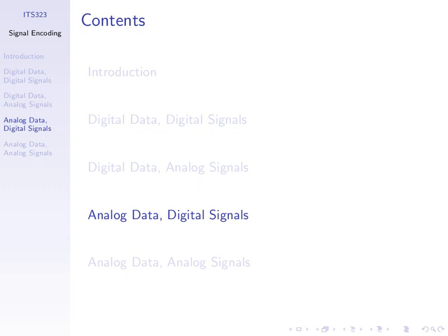So to transmit analog data as analog signals, one thing we often do is shift the analog data from a low frequency up to a higher frequency, and we perform some modulation. We'll go through how that is performed if we get time at the end. So an analog signal comes to my wireless receiver here, and that sends down to the amplifier, and in fact it converts back to the original analog signal from the microphone, back to the normal 0 to 20 kilohertz.